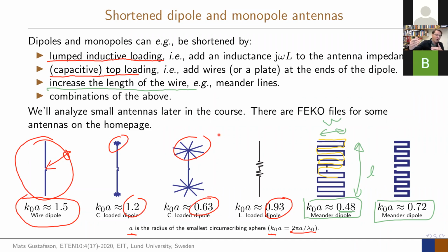So you can take your half wavelength antenna and start bending the wire. It fits on a much smaller scale, but you can still get effectively the same length. It's not exact, but it's approximately there. Now you start shrinking your dipole antenna. It will not affect the radiation pattern much. It can lower it a little bit from the half wavelength one, and it will get closer to the Hertzian dipole. But that's a small effect.